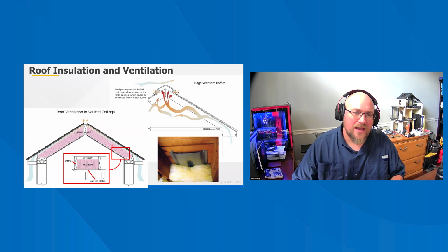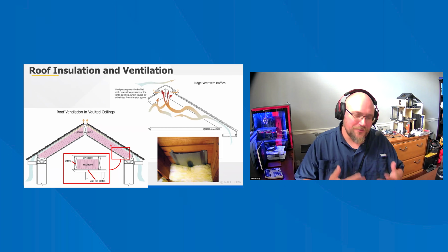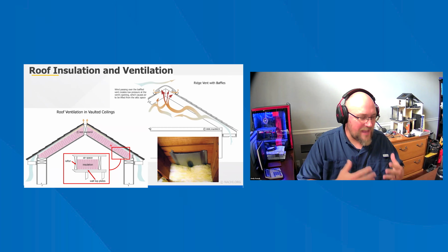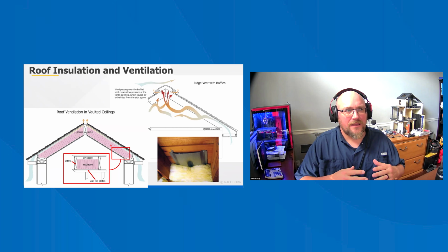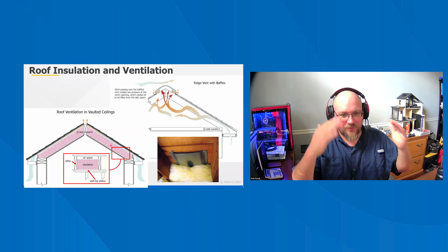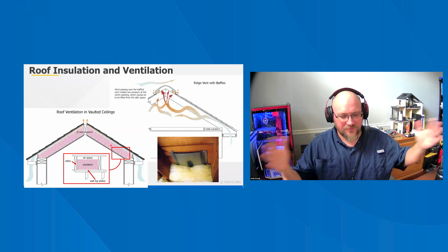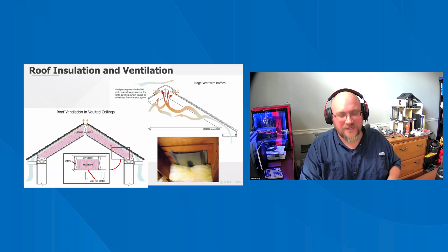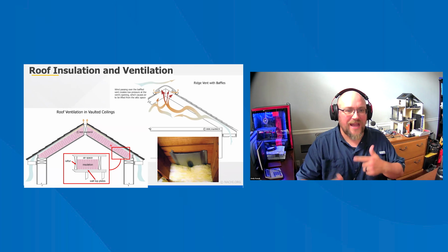Luckily, I think the homeowner did not use that part of the house. They spray foamed the roof decking, right? And it was a really small attic space, but then they terminated the bathroom vent up into that attic space. And so there was no airflow.